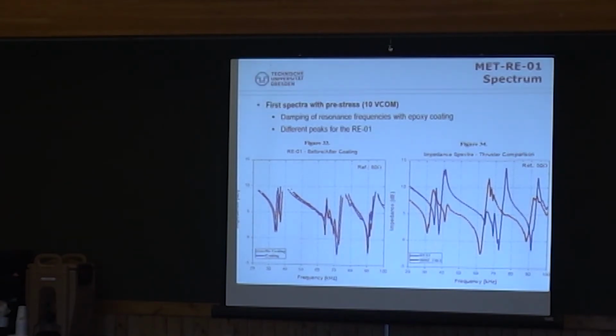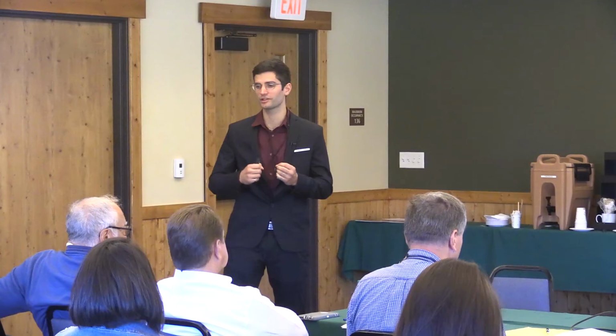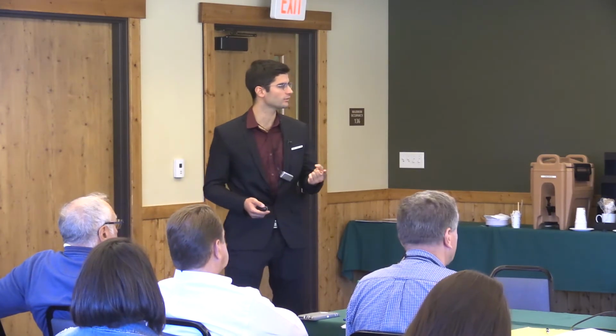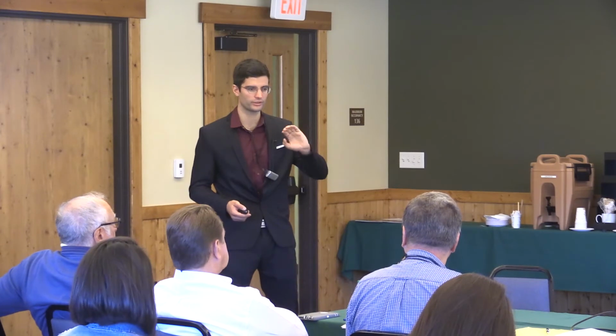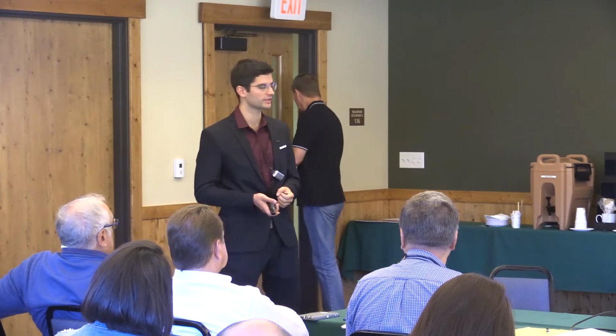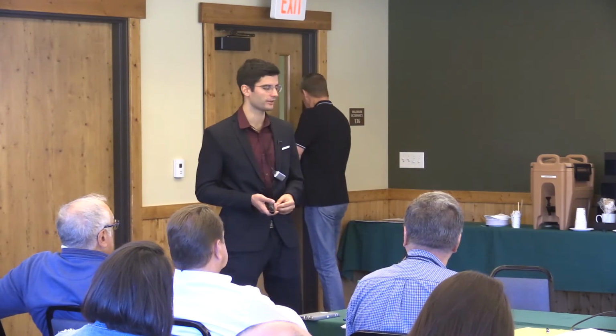So this peak actually is what I expect from FEM, from modeling. And there's a second peak right next to the first resonance, which I don't know where it comes from. But basically the unloaded impedance spectrum would be a very good way to characterize your mechanical systems and make sure that it's built the right way, or built as designed. And I would be interested to see what difference the dome configuration, or the way you clamp it with the brass mass, Jose, would have on the impedance spectrum.